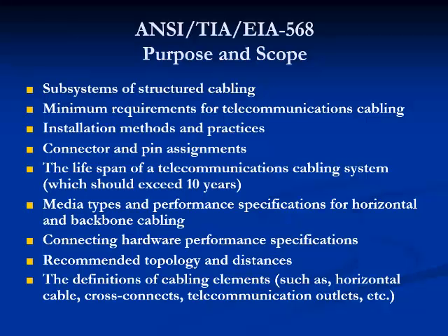In the mid-1980s, consumers, contractors, vendors, and manufacturers became concerned about the lack of specifications relating to telecommunications cabling. Before then, all communications cabling was proprietary and often suited to only a single-purpose use. In 1990, TIA and EIA published the first version of the commercial building telecommunications cabling standards, better known as TIA-EIA 568, or sometimes simply as 568.